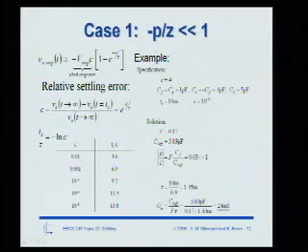And in this particular example, going back to this example, calculate your F factor. Remember, F is not 1 over C. Calculate your effective load capacitance. Then you check P over Z, which is F times the ratio of CF over CL effective. In this case, it's 0.03, which clearly is much less than 1, and so we have no trouble neglecting that 0.